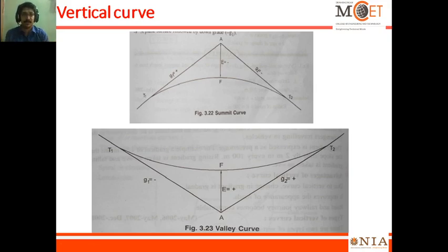In the horizontal circular curve, we can pinpoint the I point or V point on the ground. But in the vertical curve, the meeting point is in space. We have to assume it will meet here, such that the curve is like this, depending upon the grade and how much smoothness we have to provide. Sometimes the G1 and G2 numerical values may be the same, sometimes different, right?